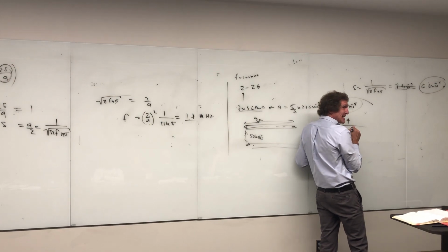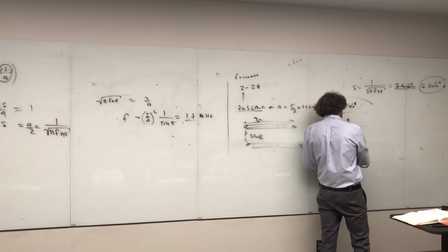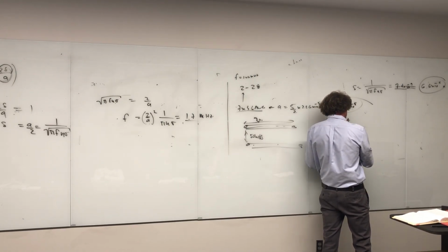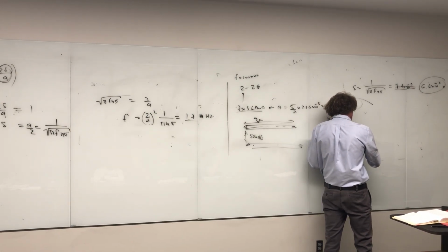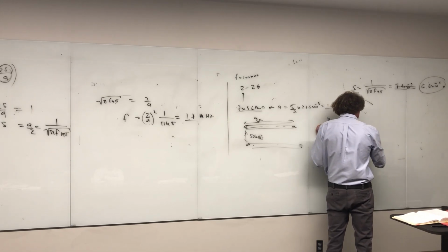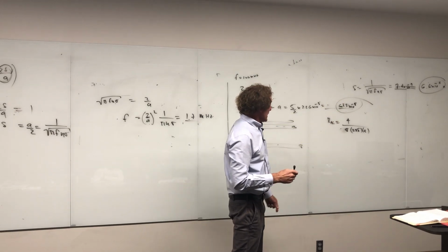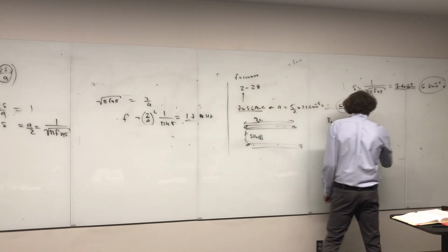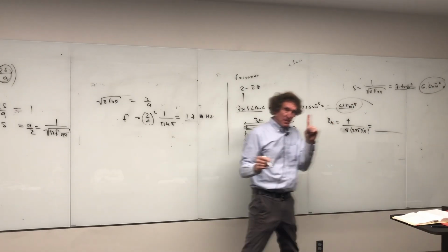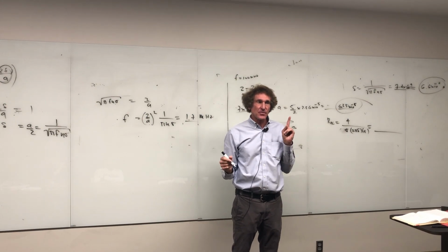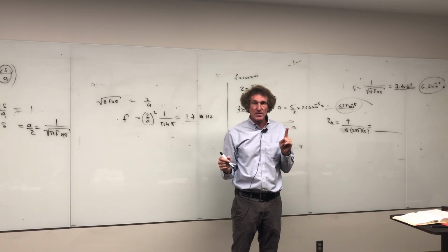Now you divide that by sigma. Really, you can divide it by 2 pi, right? Actually, let me do it. I'll put sigma first because that way you'll get used to this. Sigma is going to be 5.8 times 10 to the 7th. Then it's times the area. This will be 2 pi times skin depth times radius right here. So you've got radius, skin depth, and 4 times this. And this will be the AC resistance of just one wire. Tell me what it is. Remember, not just one. There's 7 of them, so we're going to divide by 7 in a second. Do you all agree with this?